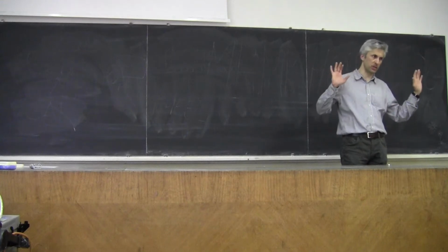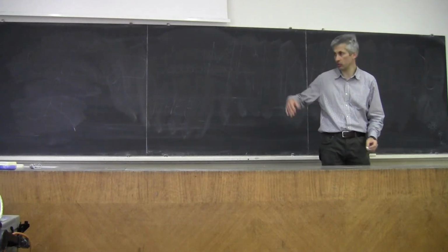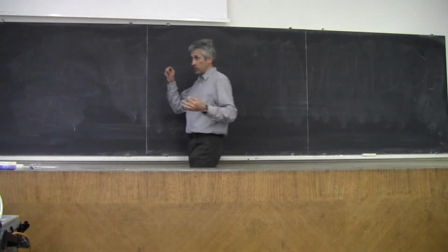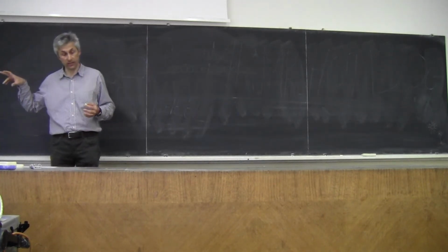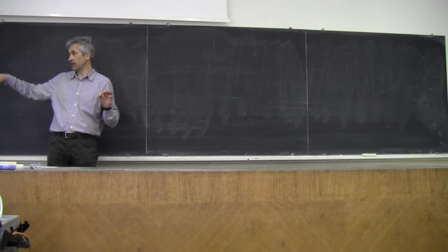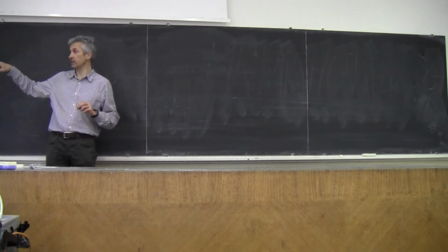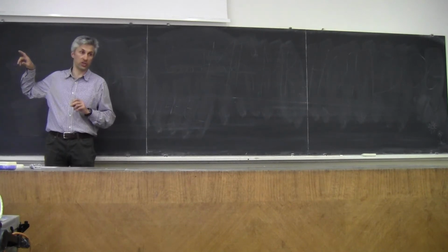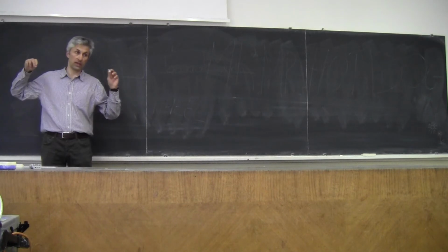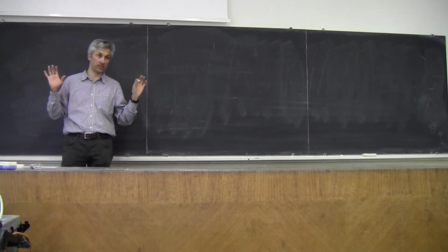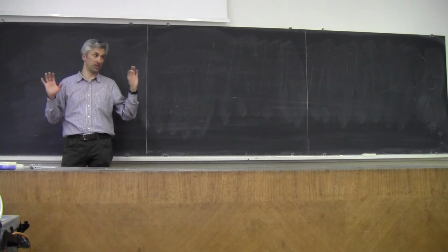We will see later how to compare the simulation with the reality and how to adjust the time area relationship and the runoff coefficient C, to adapt the model to the observations, to maximize the fit of the model to the observations.